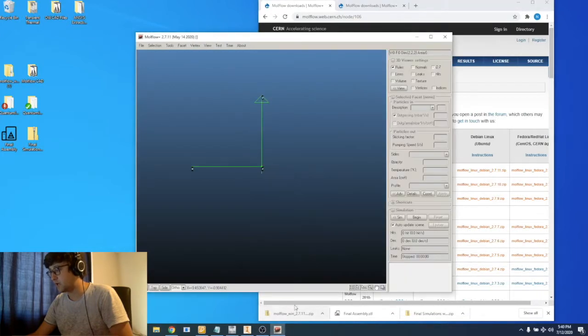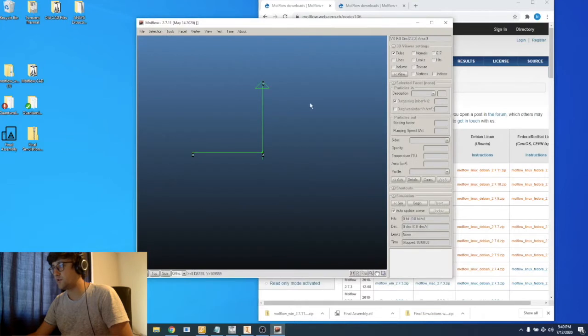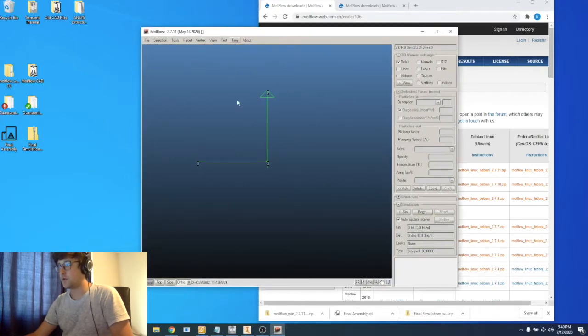So you can see this little molecule icon, and this is your starting point. I'll just go through the basics of what I would do if I'm going to simulate a vacuum system. You can use this for other things, but maybe I'll make another video. In general, you're going to need some kind of STL file to import into here. You're going to want to make a simplified geometry, because when this generates a mesh, if you have something super complicated in a really complex Inventor file, the mesh might not fail, but it's going to be unnecessary for what you're trying to do.